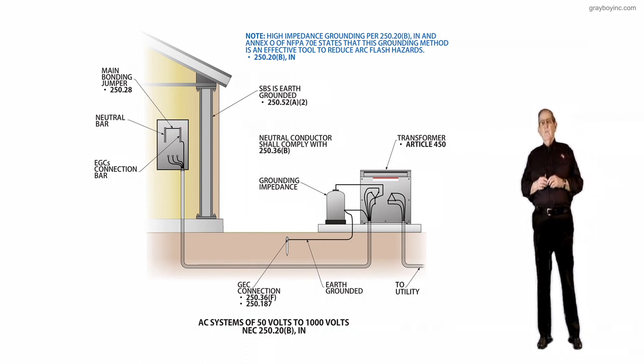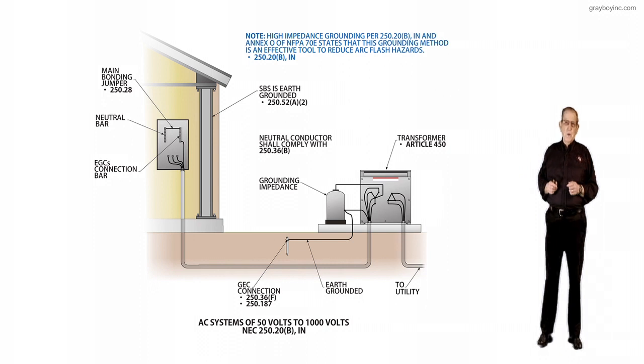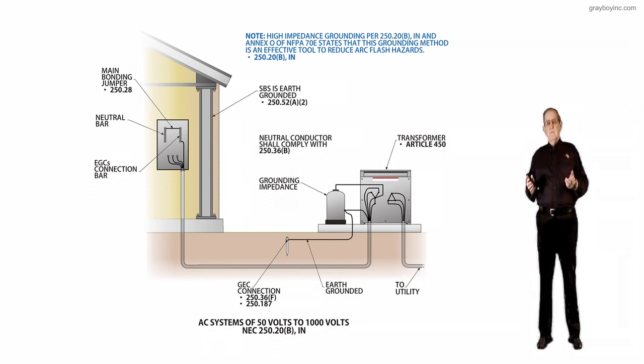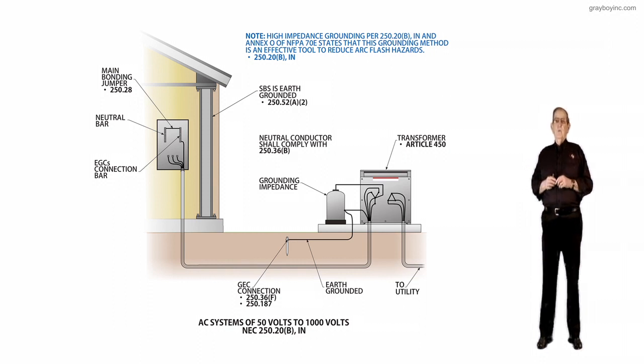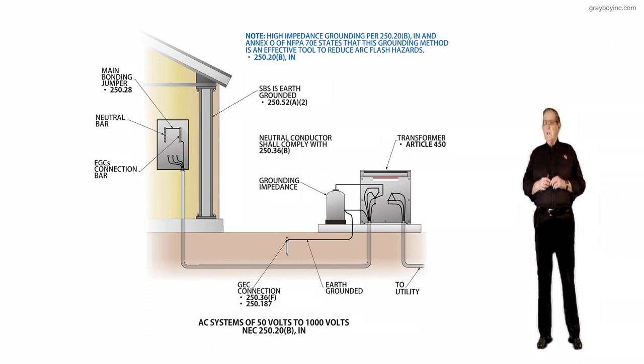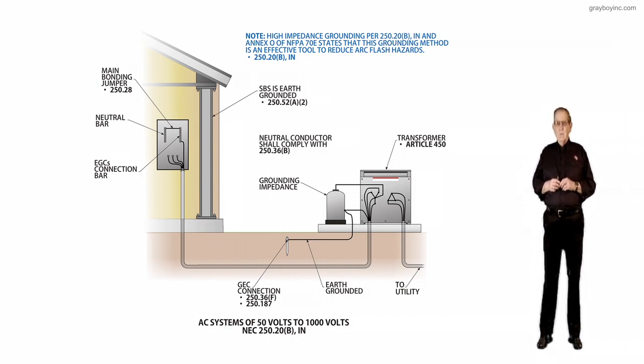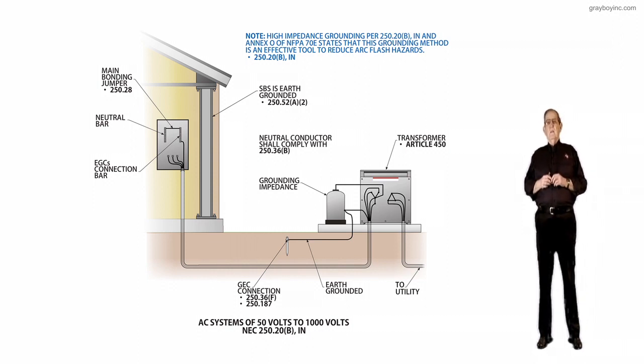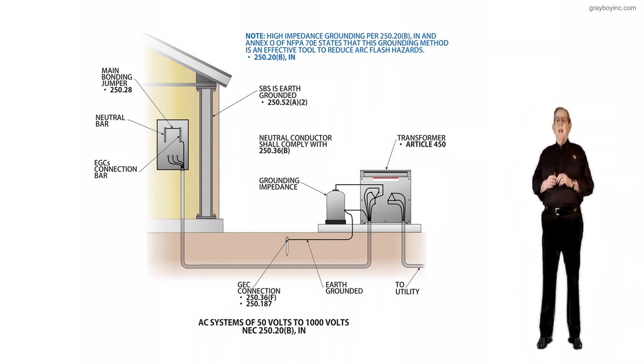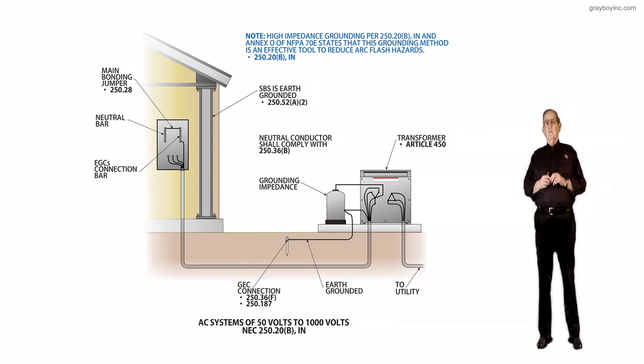However, you could go over and review 250.21 and you have a choice. You can either ground the transformer or you don't have to ground it in that manner. If you go over to 250.22, then you cannot ground the transformer and it is listed there. You'd use an isolation transformer or a type of transformer that would comply with 250.22.